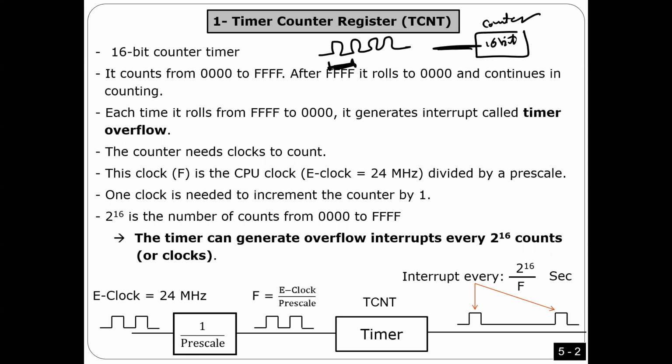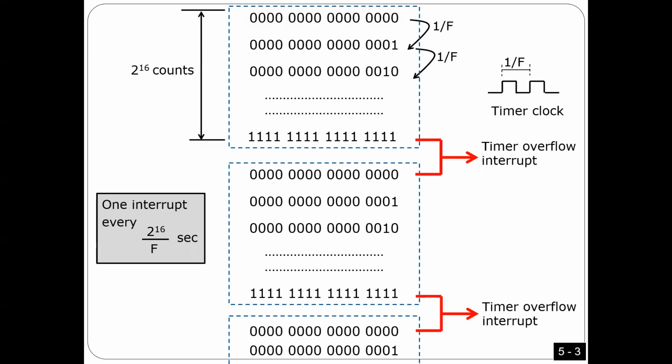This is a hardware circuit. I call it a counter. It's 16-bit, right? In order to count, this counter needs a clock. I think in a digital systems course you should have designed a counter, I guess. Anyway, it's a hardware digital circuit, and this digital circuit needs a clock, right? And the idea is, for every clock cycle here, the hardware circuit is going to increment the counter by 1.